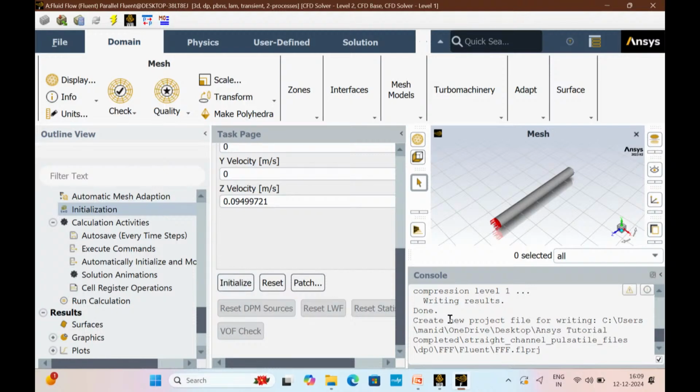Because the simulation is starting from the inlet, if we provide this type of velocity profile, will they take a constant velocity or a parabolic profile? This profile is time dependent, meaning the x axis is time and the y axis is velocity. If we draw the velocity at a cross section, it will be parabolic. Yes, for this case. But when we do simulation in a bifurcating channel or channels having stenosis, like converging-diverging channels, flow separation can occur. Talking about the inlet, yes, it is parabolic.